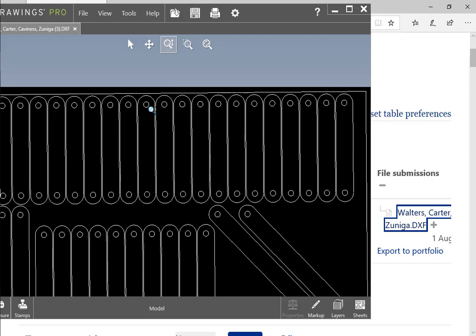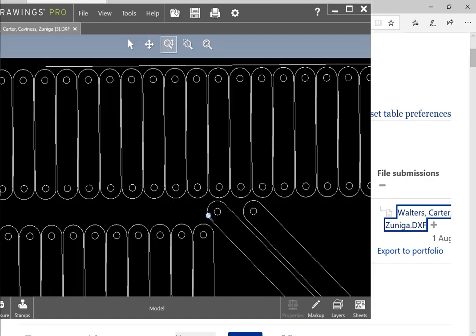It's easier to remove them in SolidWorks because you can hide all the annotations versus clicking and deleting every one of them, which would take a while. If you don't get rid of those, I don't know of this person who's cutting the trusses, if they're the kind who go in and delete them for you, or you just get all your pieces back with little cross marks cut into all the ends of your members.